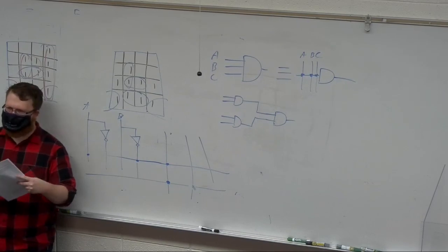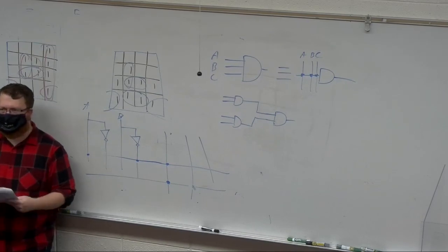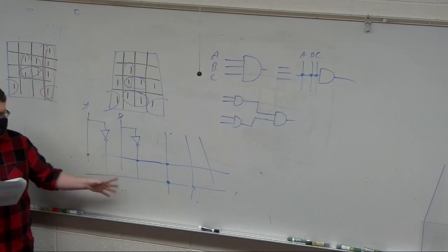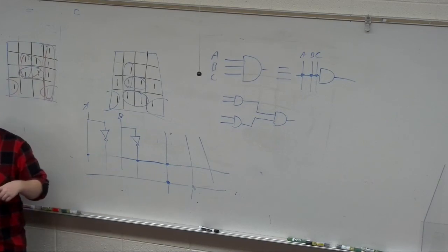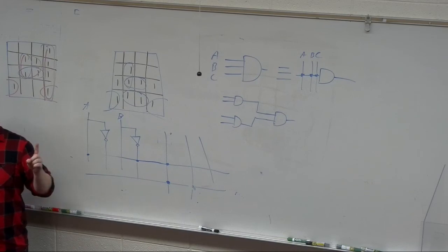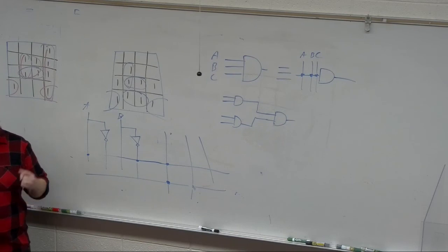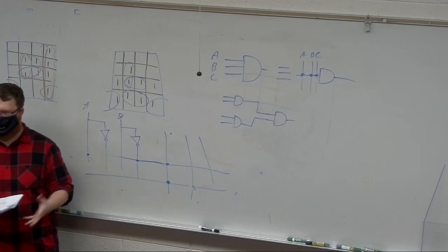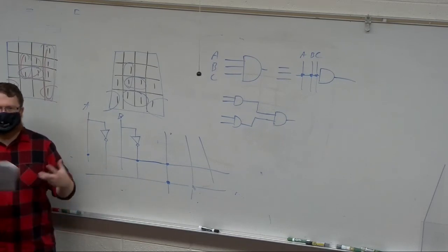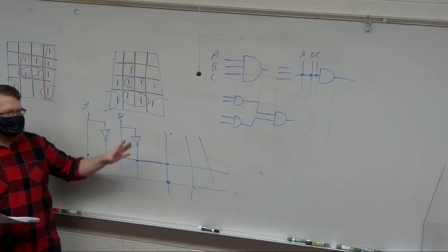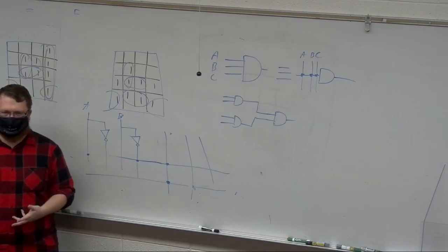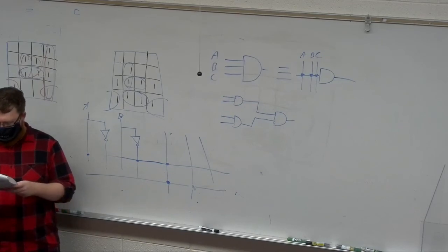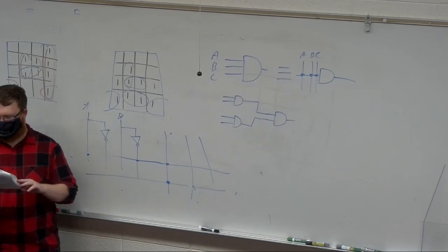Only the AND gates are programmable, yes. So you can't program the ORs in a PAL. In a PLA, you can do the ORs and ANDs. In a PAL, you cannot do the ORs. This makes them less expensive to design because you only have half as much programmable, but it also means that you can no longer share AND terms at the OR gates because the OR gates are predetermined.